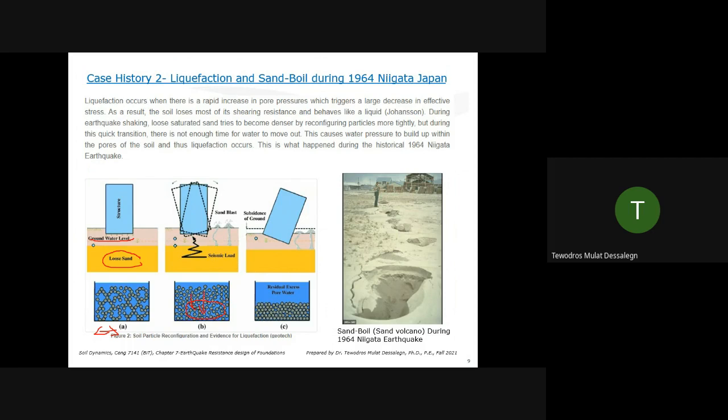And that high water pressure is sufficient to go up through here. You see it here. The water pressure is escaping like a fountain, and with it, it takes a sand deposit with it. And once you have this, what happened? There are some instabilities happening. The whole thing is now turning into a liquid. The sediment particles are going down, like here. It was compressed water. Now you have semi-liquefied soil.